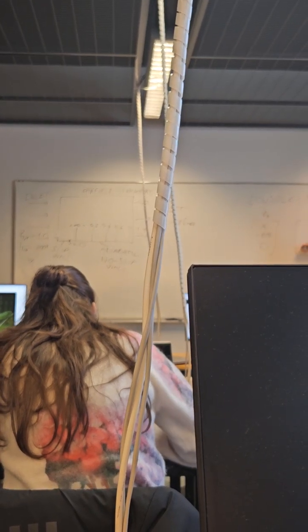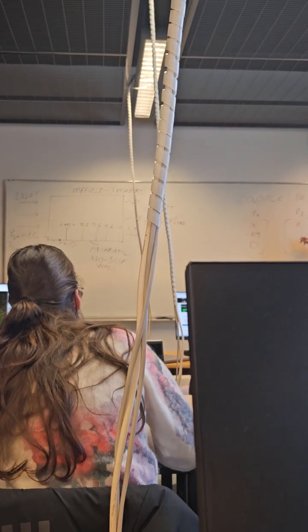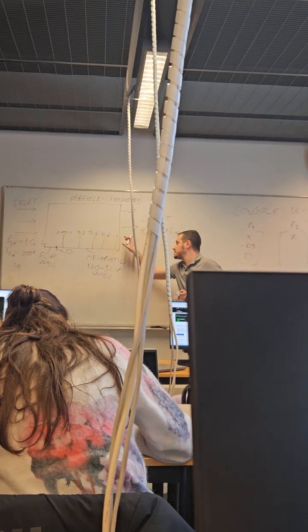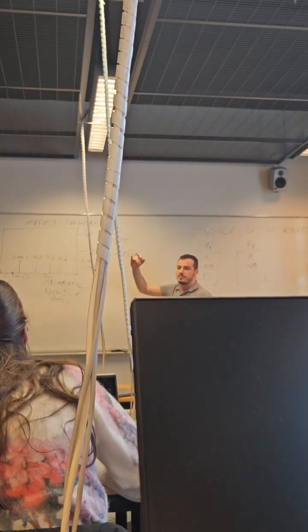Then x goes 0.1, 0.2 until 1.5, with the same y in the center of the domain, but we need to choose a z value that covers at least all the boundary layer. With 0.1 we are already fine. We can check later when we plot the line.